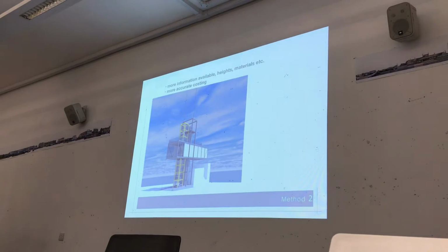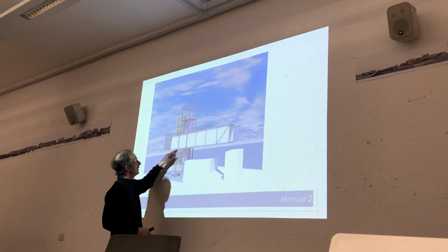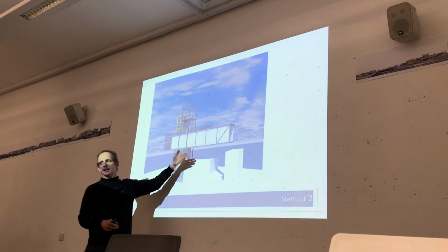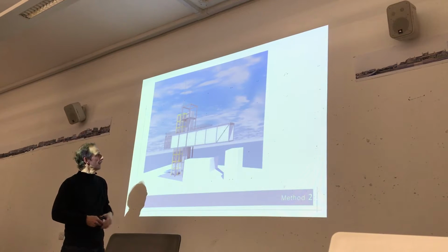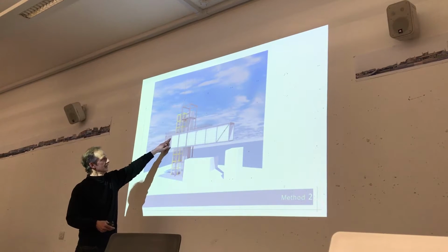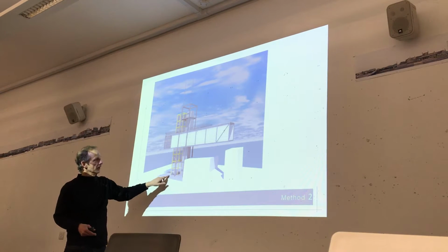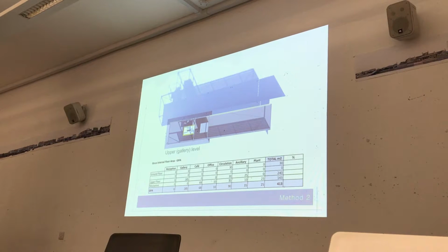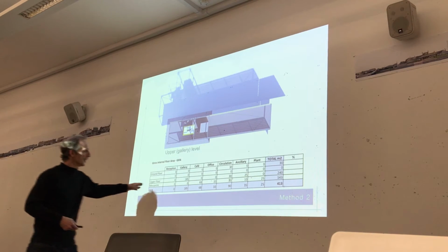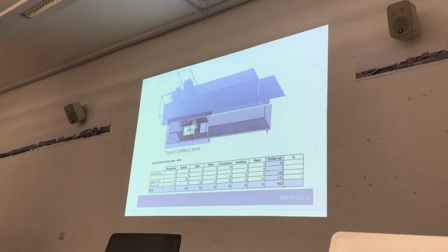Yeah, it's the same thing. So on this, you're going to be measuring what the wall finish is on the outside and what the wall finish is on the inside. Those are going to be two different elements, or it might be part of the same build-up. What is your structure? How much of it is glass? What's your lift shaft? Is that concrete? How much foundations have you got? The more foundations you've got, the more expensive it's going to be. So this is how my floor area is built up on that one. That would go into that spreadsheet and start to calculate those things.